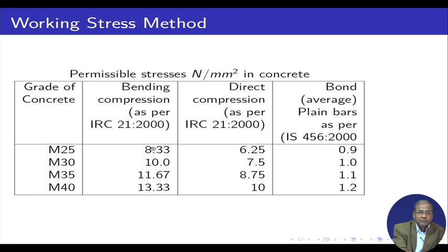So, that is why in this working stress method, whatever formulation we have, we assume these values with a certain safety factor. The partial safety factor we shall come to later in the limit state method, that word partial is equally important there. Here we are considering a safety factor, and if we consider this one as 3, then here we can say 4. So, on the basis of that we can correlate with FCK only.